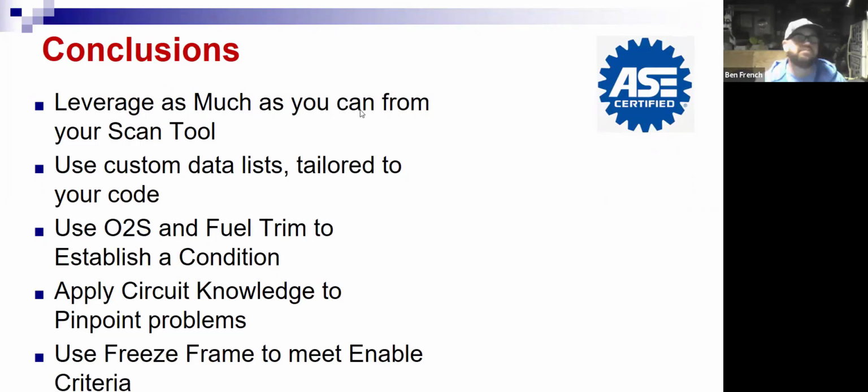All right, so leverage as much as you can from your scan tool. So tonight, when we think about leveraging our scan tool, we talked about building custom data lists. We talked about graphing that data and tailoring what data you're looking at to the code that you're fighting, the big 6 and the great 8 data parameter PIDs, right?